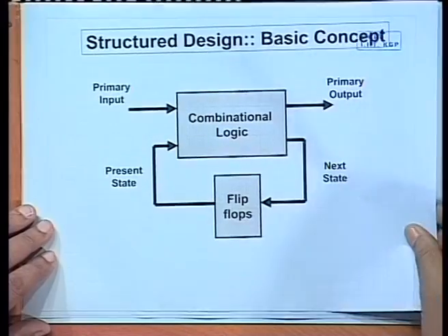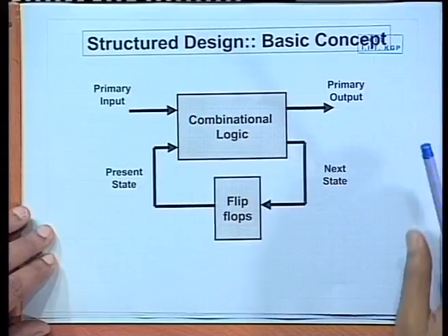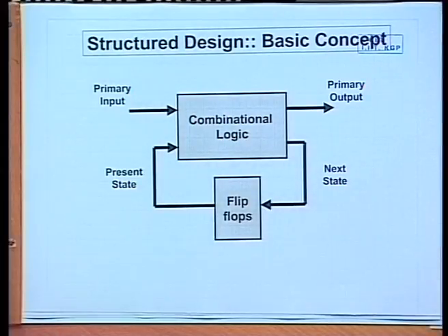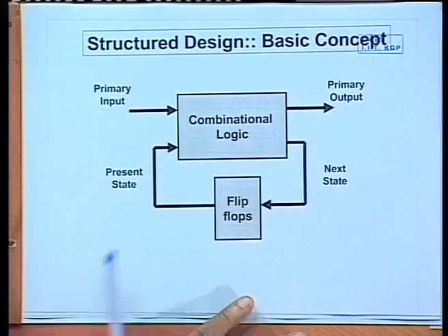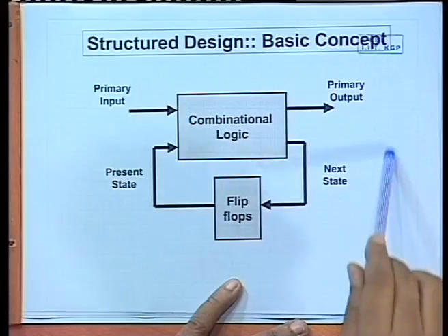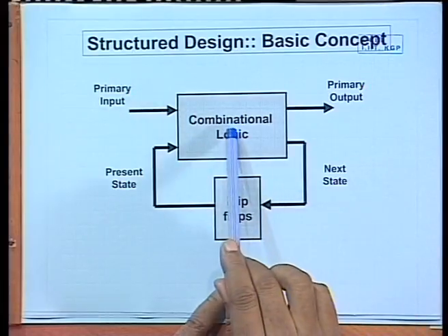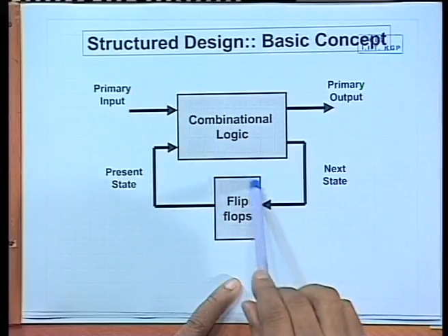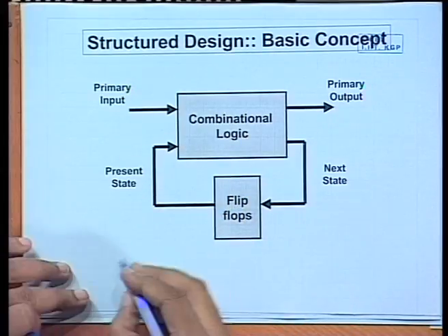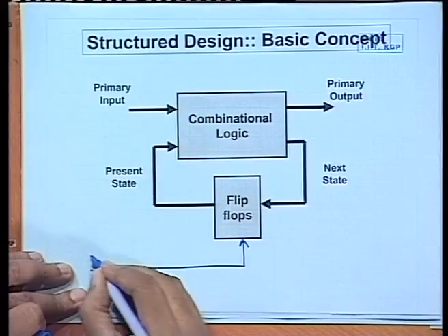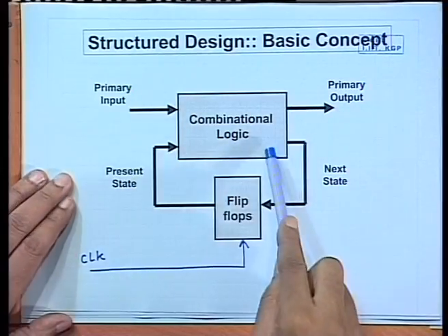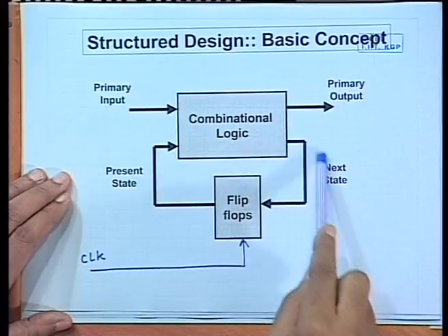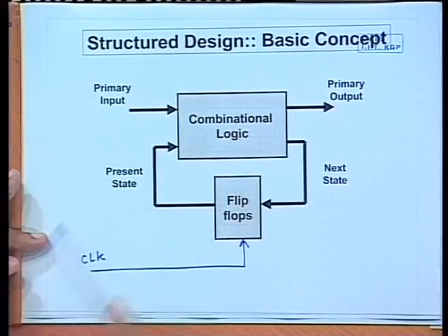Structured design tries to attack the problem from a different viewpoint. The structured design for testability techniques are primarily aimed at testing sequential circuits, and as you know, a sequential circuit can be modeled like this, where the combinational portion and the memory portion, the flip flop portion, can be separated out. Of course, I have not shown the clock, which will be feeding the flip flops. Primary inputs, primary outputs, and the state variables: this is the present state and this is the next state. So, when the clock comes, the next state becomes the present state.